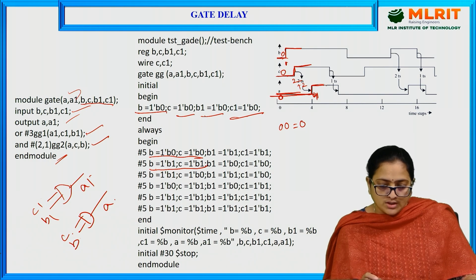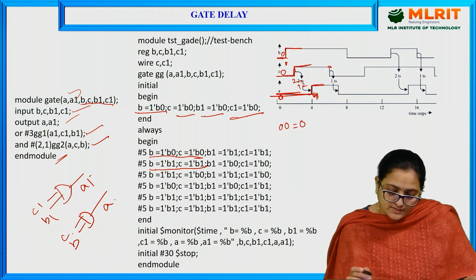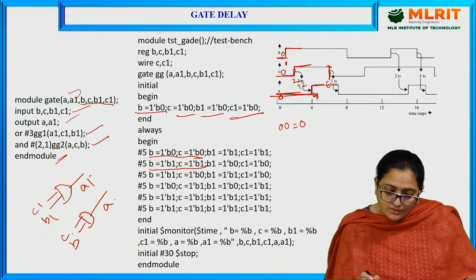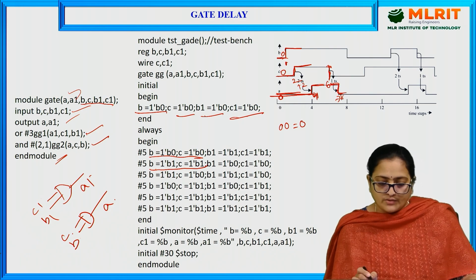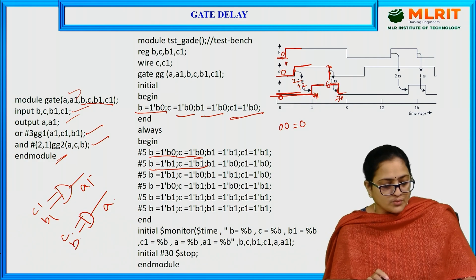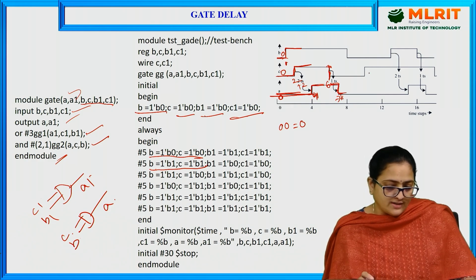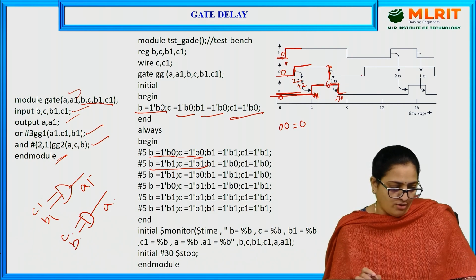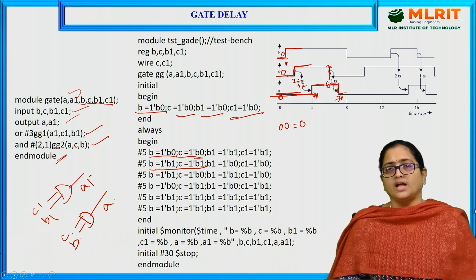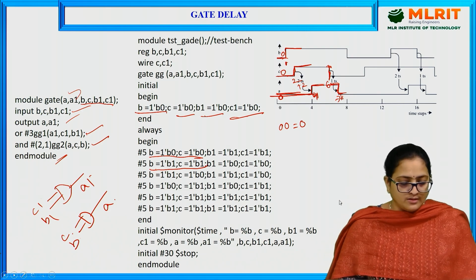And coming to a negative transition, here see, let us assume this has occurred at some 6 time intervals, but it has taken 1 time interval of delay and it executes at 7 time intervals. It takes a negative transition at the 7th time interval. So this is how the positive transition delay and negative transition delay can be analyzed in waveforms. Just here I have taken an AND operation to explain, and similarly it can be applied for OR also.